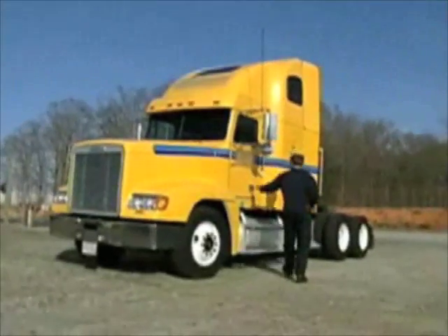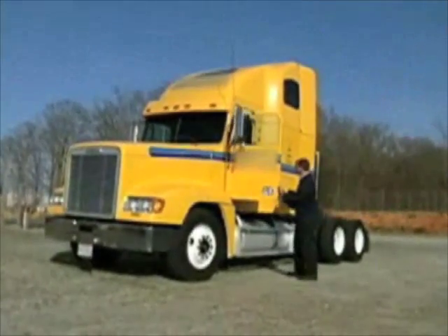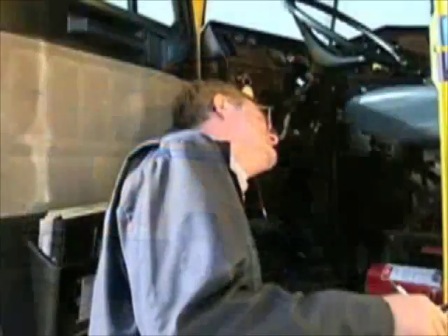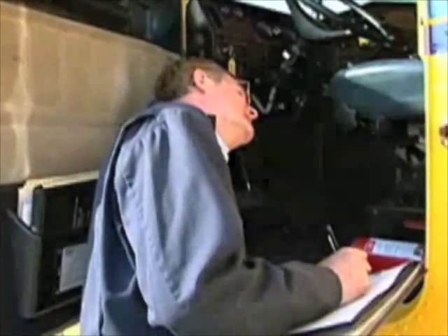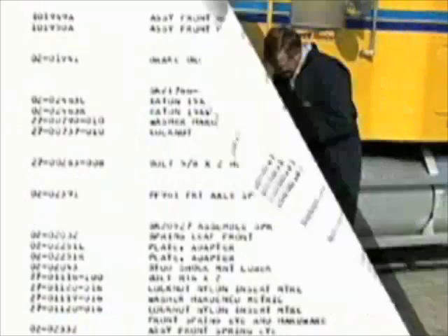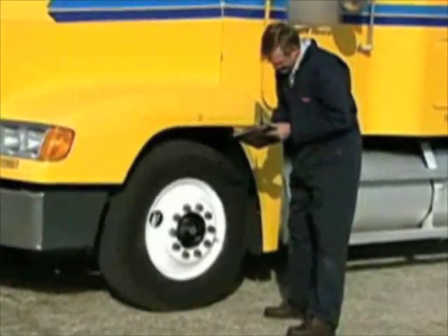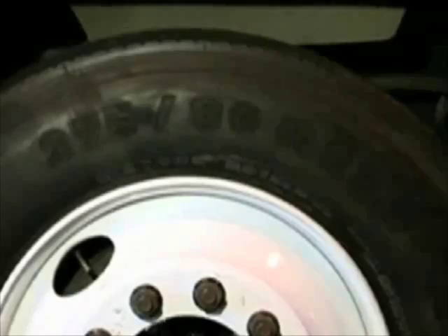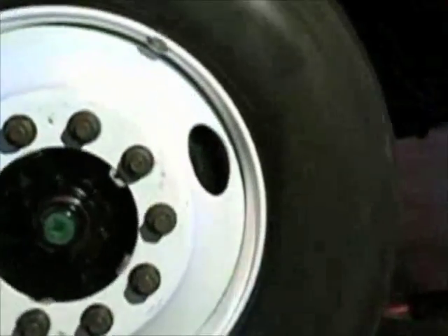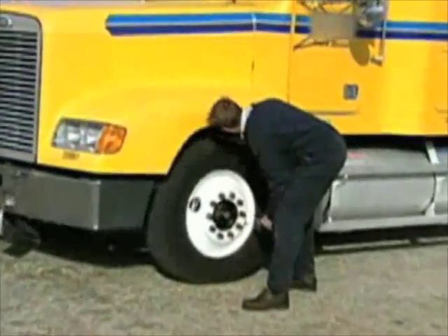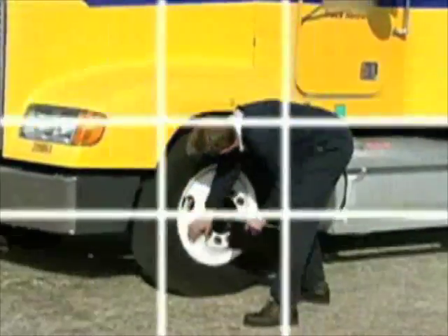Using a vehicle inspection form, record vehicle information such as make and model, date of manufacture, mileage, axle information, etc. A manufacturer's line sheet or spec sheet can be helpful in providing this information. Next, record all tire facts, including type, size, air pressures, tread depths, and balance weight amounts and location. Take time to note any tire wear conditions you see.